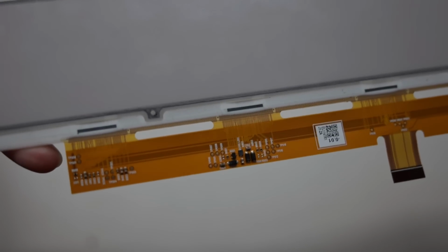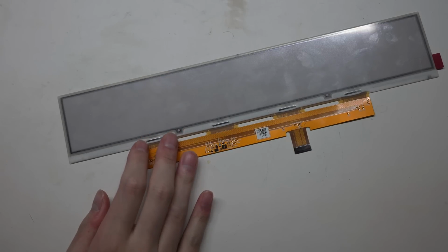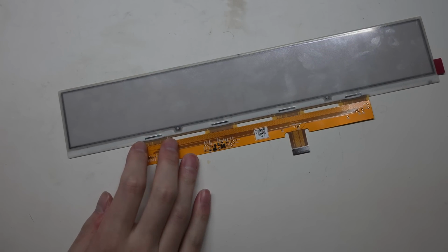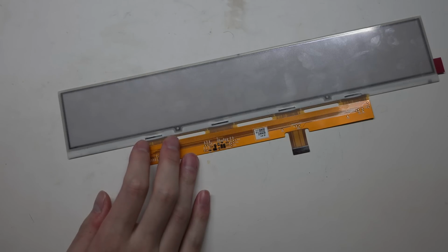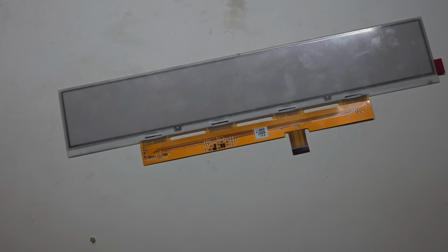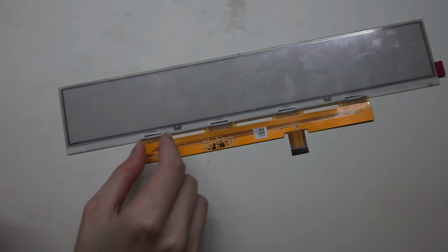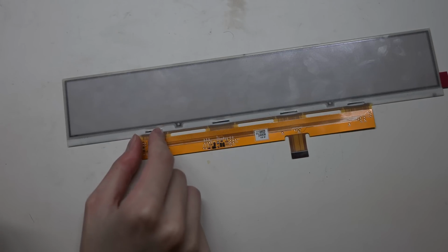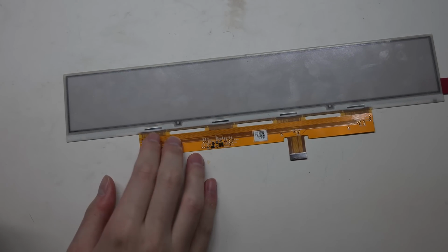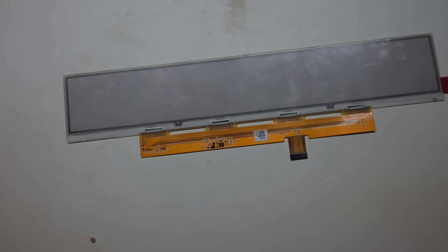So guess what? Different chips have different sizes. As I said before, there is a finite number of E-ink screen driver chips. If I just go through every one of them, check their size, and find the one that matches this size, then it's likely the one I'm looking for. That is what I'm going to do. I'm not going to measure it under the camera, but I've already done it. This is about 13 millimeters by 1 millimeter. And we're going to see if I can find any matching ones.